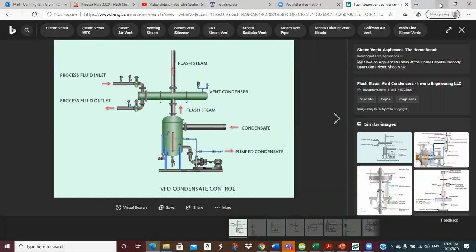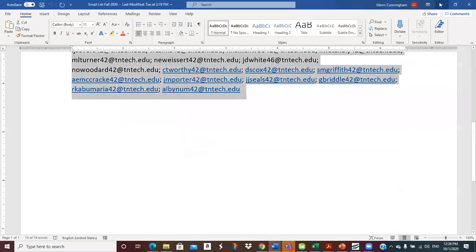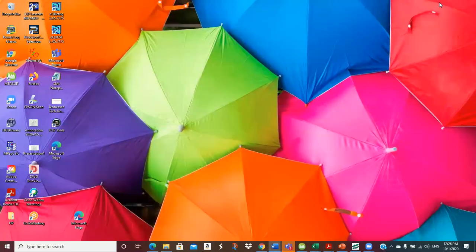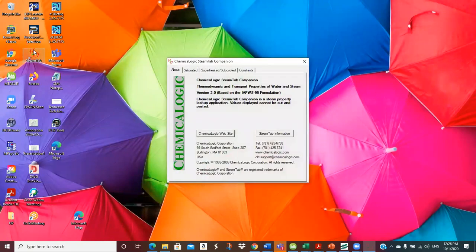Okay, so let's do that real quick. This is what I was going to do and get on my paper, but this one never made it to the paper yet. Oh, man. All right, so here's my little. Well, come to think about it, we had those numbers, right? It was 1150 on the saturated vapor and 180 on the saturated liquid. So it's 1150 minus 180. So it's 970 BTUs per pound that we condense. Okay, and I'll just run 2,300 pounds times 970.